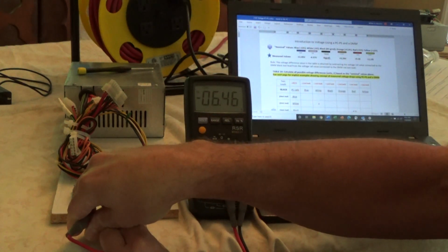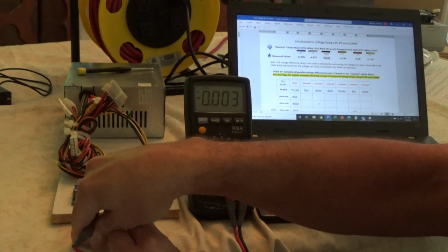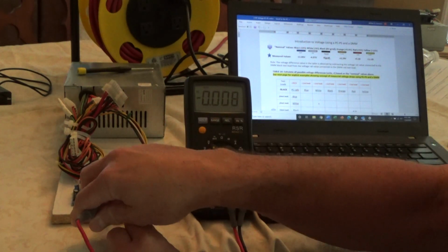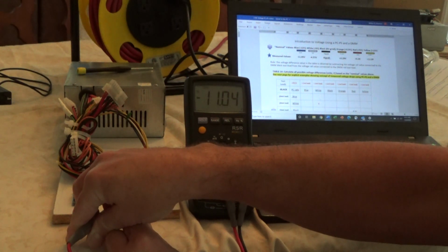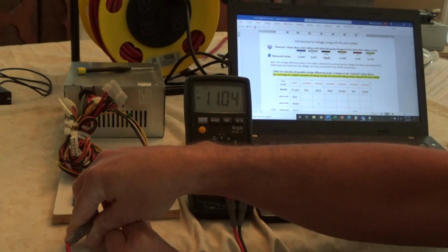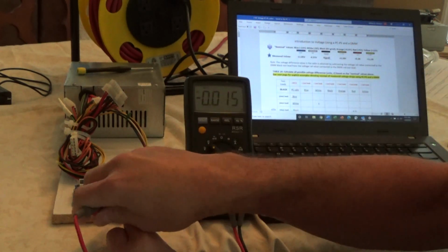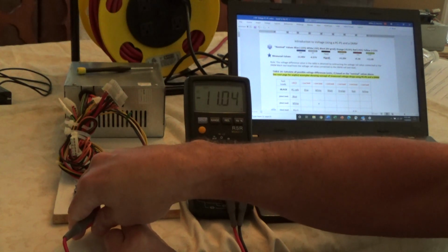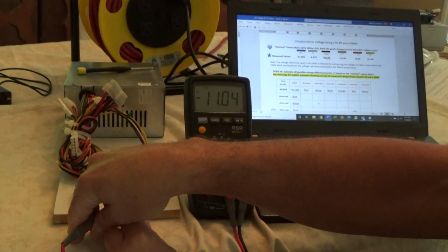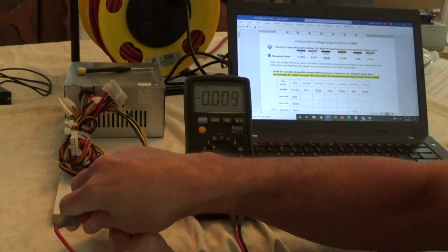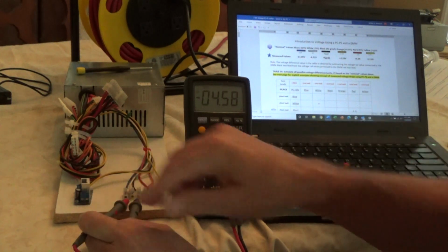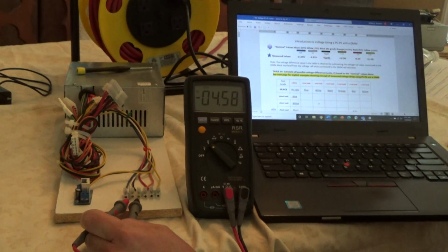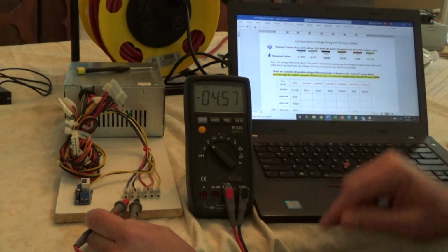Okay, so basically we see, whoops, that's the wrong rail. I got the black rail and the blue rail. Making all kinds of mistakes here. Okay, negative 11.04 volts. Now notice it's changed a little bit. These values can drift. So I had a negative 11.05. That's okay. We'll just stick with it. Okay, so, there we go. Negative 11.04 volts. Now let's go to the white rail. That's the next value. See, it's not really negative 5. It's negative 4.57, negative 4.58. See how it's drifting a little bit? So anyway, that agrees with what I measured earlier.